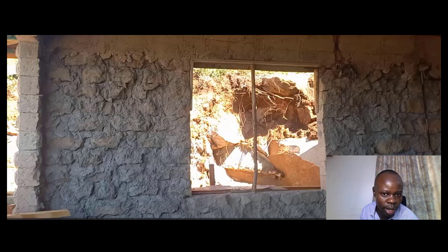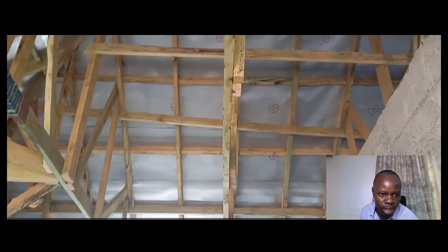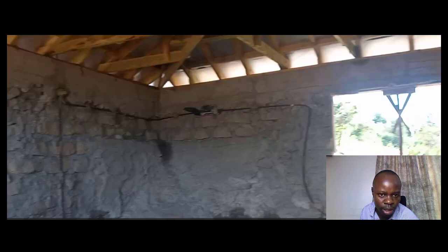I believe somewhere when I started, let's have a look at just somewhere here. Yeah, this looks fine. You realize that when you're doing your areas in square meters, it's always from the finished floor level to the top of the soffit of the ceiling.